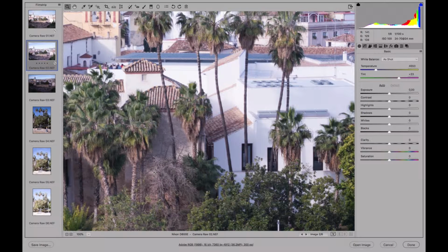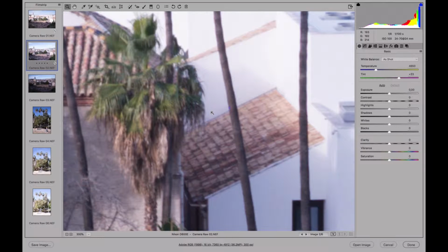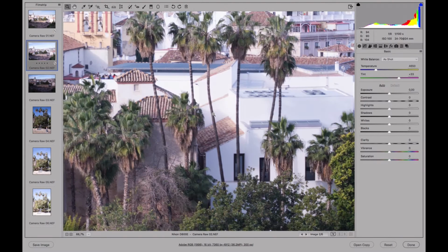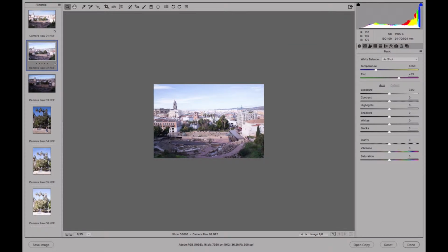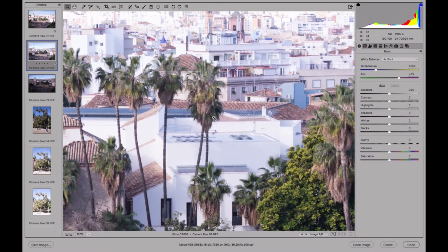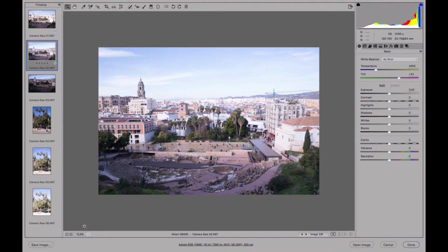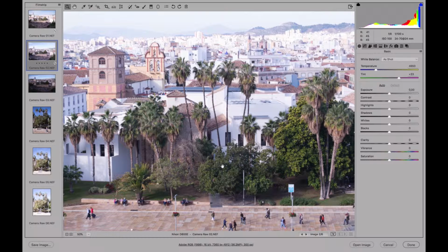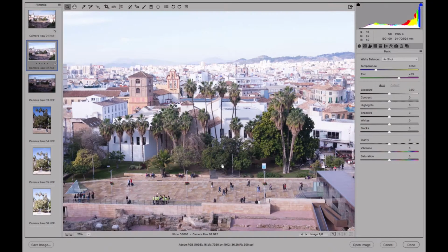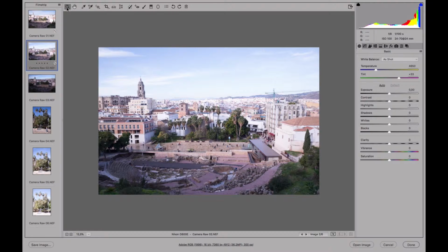So, if we want to see the photo at its biggest size, we'd be looking at 100% of the photo. We can also do that with this tool up here, the magnifying glass. Clicking on the photo, we can amplify it, and with the Alt key pressed and clicking, we can zoom out. So, we won't do anything. We'll zoom in, press Alt and click, and we can minimize it. We can also do that here, and with the keyboard, Command Control plus and Command Control minus, we can also do it. So we can also use it to change the size.